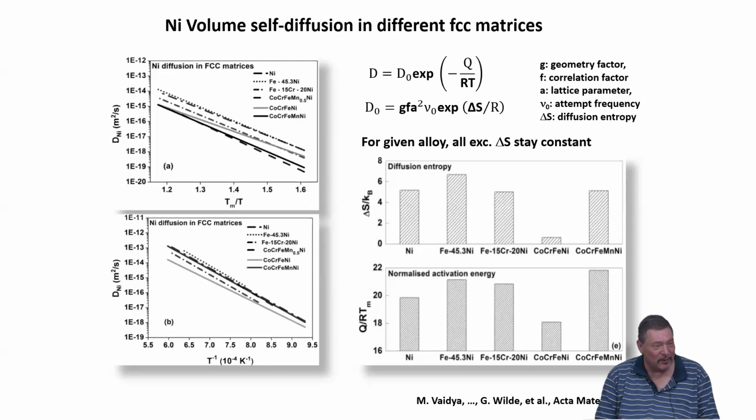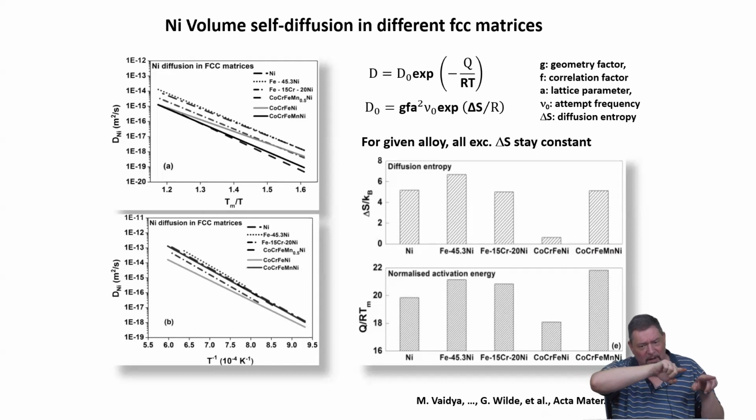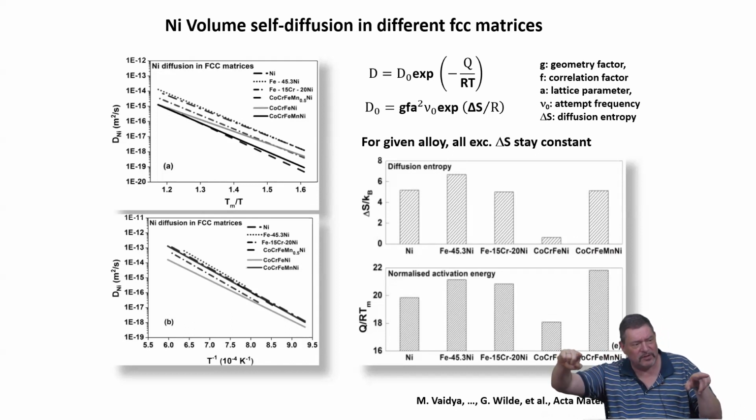Yeah, Cottrell locks, Lomer locks are very, very easy. For those who have not advanced to the higher studies on dislocations: dislocations are line defects. They can interact in multiple ways. And some of these ways involve splitting up of a perfect lattice dislocation into partials. So one partial goes first and the other one trails behind.